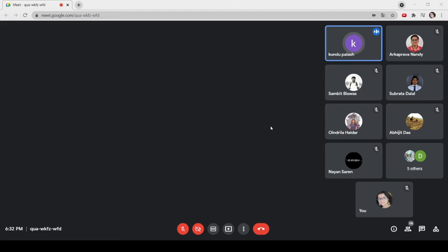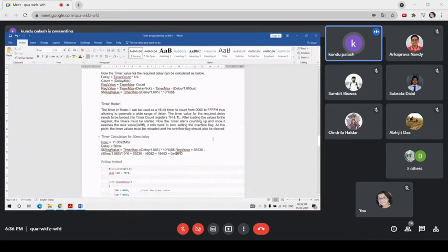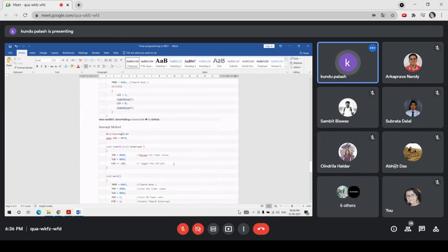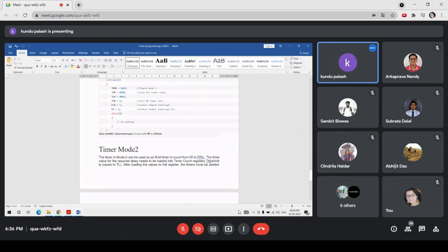For example, the timer operated under mode 1, you can calculate for 16-bit, because timer 1 will generate the higher time delay value, because the basic count register is 16-bit. We will describe this in a C program. Whenever we study that programming part, how the peripheral, especially the timer, can be programmed, it will be clear.